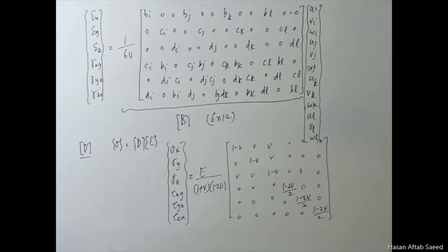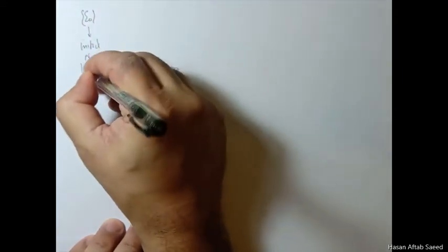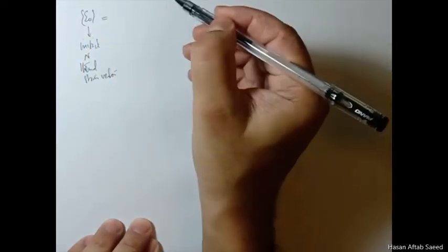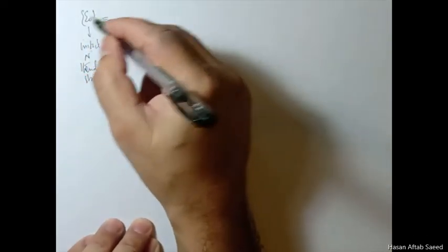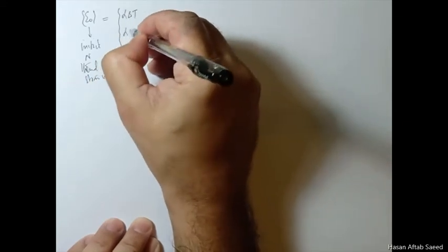This epsilon naught for 3D cases is simply the initial strain vector, or thermal strain vector, and we are talking about cases where you have a change of temperature. Obviously, if there's no change of temperature, you don't need to think about that. So let me first write it and then I'll explain it.